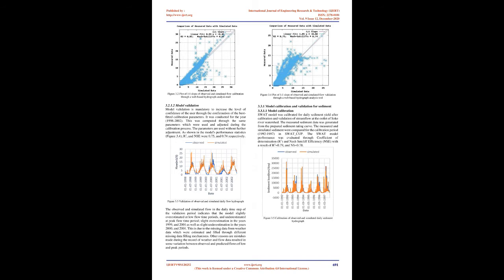3.1.2 Parameters sensitive to sediment. Sensitivity analysis was done for sediment and the list of parameters adopted is described in Table 3.3. The parameters listed above were selected for the sensitivity analysis of sediment calibration. A daily sediment data set, similar to the flow sensitivity analysis, was used for identifying sensitive parameters. The result from the global sensitivity analysis indicated that the Manning N value for overland flow, OV_N, sediment concentration in lateral flow and groundwater flow, lat_sed, and the average slope length of the subbasin were the key parameters as ranked in Table 3.3. These were determined through t-stat and p-value as described in the table.